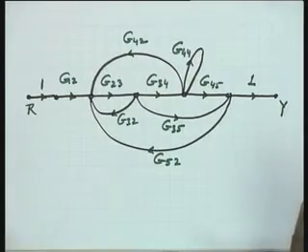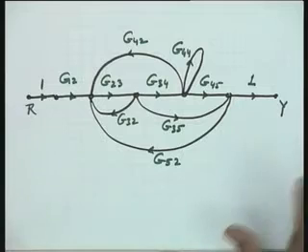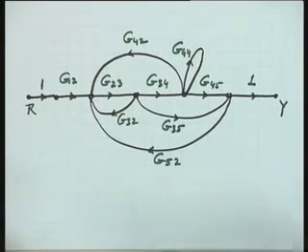To give you a slightly more complex situation, I will take this example, and you will have to give me the answer of every point regarding the signal flow graph formula. I have not given you the corresponding control system. This particular situation has been taken only to make Mason's gain formula very clear. Come on, please, you have to help me now.